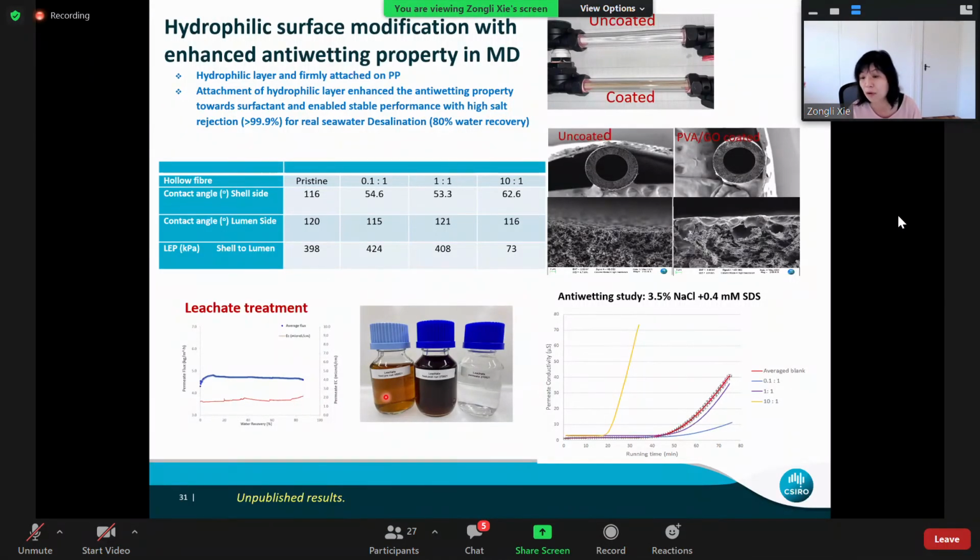And this is the original leachate. This is the concentrate, and this is the permeate. We did a full ICP analysis for both, in particular for the permeate. It has very high quality water. So actually, it rejected pretty much everything from the leachate.